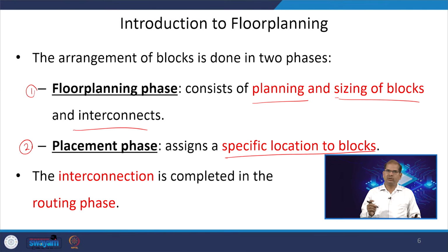In the case of floor planning, the placement of the block is not fixed. The coordinates are not exactly assigned, it is relative. But in the case of placement, the coordinates of the blocks are assigned. The interconnection of the blocks is completed in the routing phase.